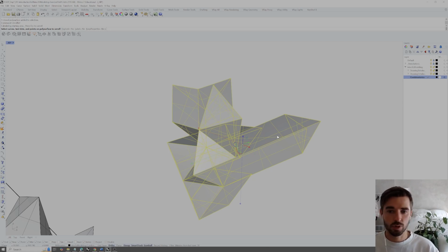But things like extrusions, most lofts, unless you use particular loft types and multiple sections, then we won't be able to do that, but that's something that we can get into. It's within options and lofts. The standard loft options with regular ruled surface sections are going to be unrollable, but this is the kind of nuances of some of these commands. But we also have a kind of base idea of certain geometric types.